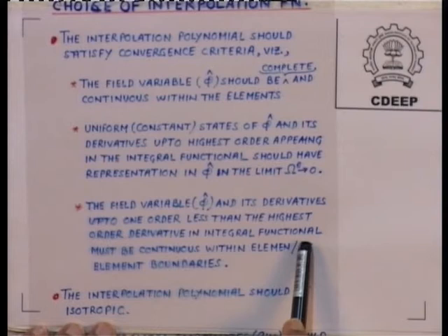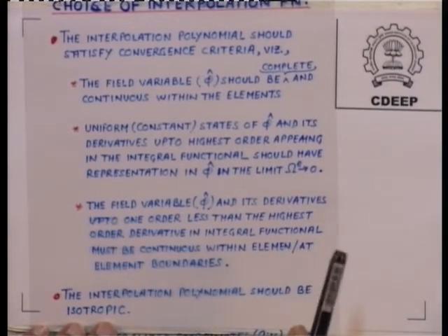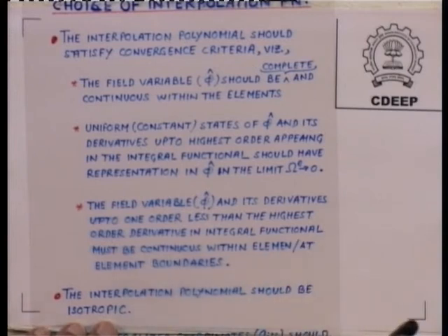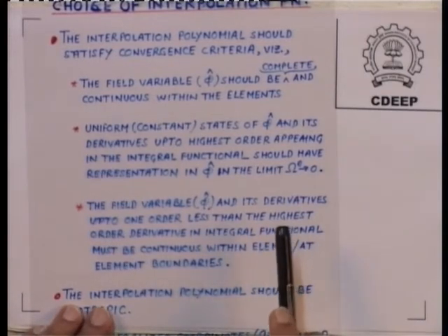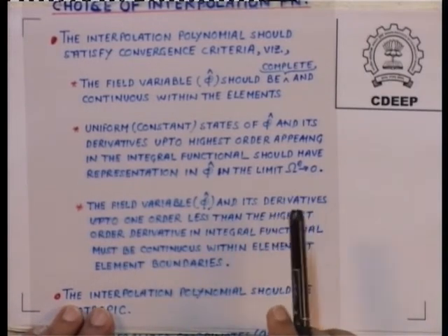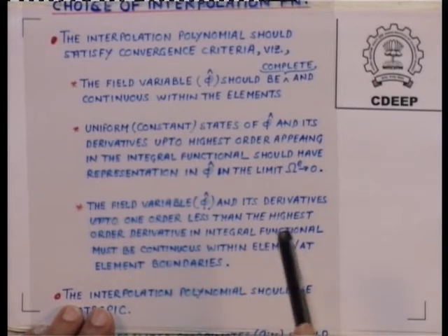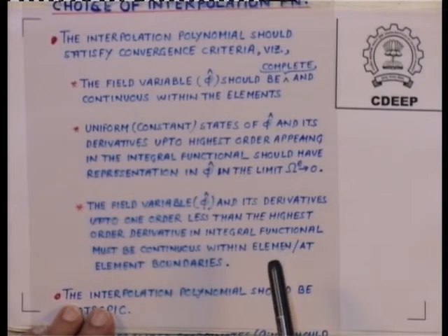Now, you may not have noted this because of the way we have done it, but in the integral you have the strain term multiplied by the E term, and again the strain term, which is why you get B transpose EB, is it not? That is the reason why you get that. So, it is the strain term. Now, strain is the first derivative.